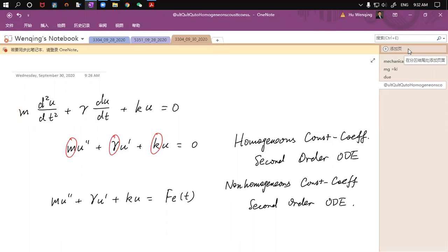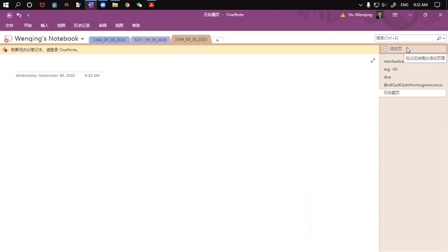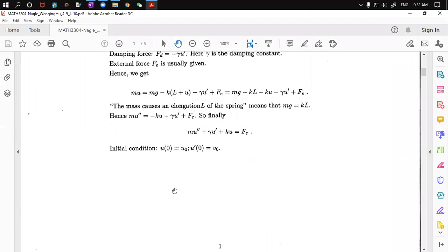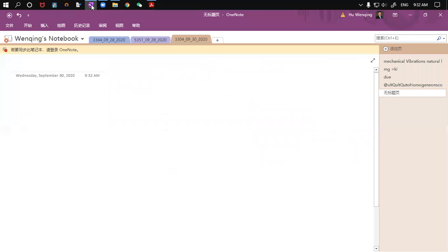Now, as long as we have both of these remarks, we now have a nice model for my differential equation, right? So it's going to be m u double dot plus, remember, the damping constant in front of the first derivative, Hooke's constant in front of the zeroth derivative, and the external forcing on the right. So that's going to be a differential equation that describes the relative displacement u as a function of t. But this is not enough. Why?